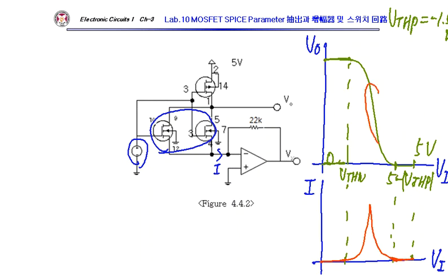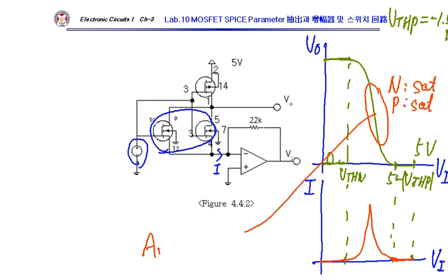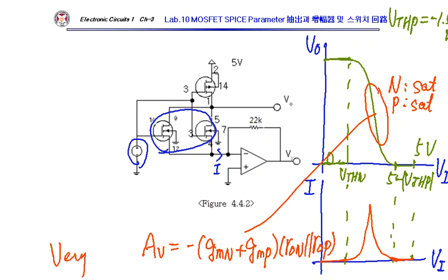So this is a very high gain region, both NMOS and PMOS in saturation. Okay. Yeah, the voltage gain here is just (GMN plus GMP) times RON parallel ROP. Okay. So this is pretty large, very large compared to NMOS alone.